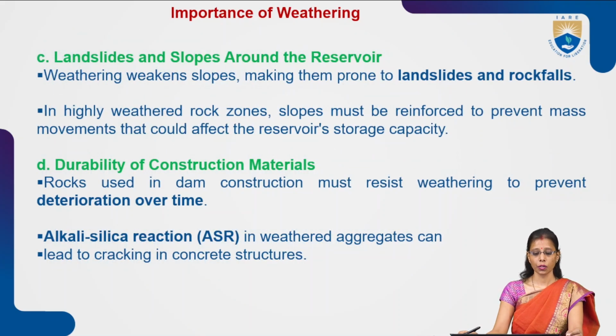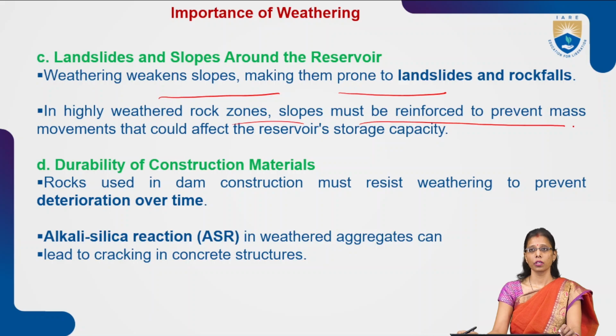Now, landslides and slopes around the reservoir. Weathering weakens the slopes, making them prone to landslides and rock falls. In highly weathered rock zones, slopes must be reinforced to prevent mass movements, which could affect the reservoir storage capacity.